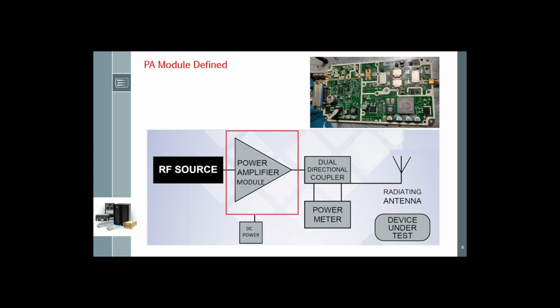And important but not shown here, the module will typically have analog I/O for temperature sense, bias current monitoring, an alarm, and a PA enable, for example, that you'll need interfacing to. And digital I/O, including gain control, is available in some cases.